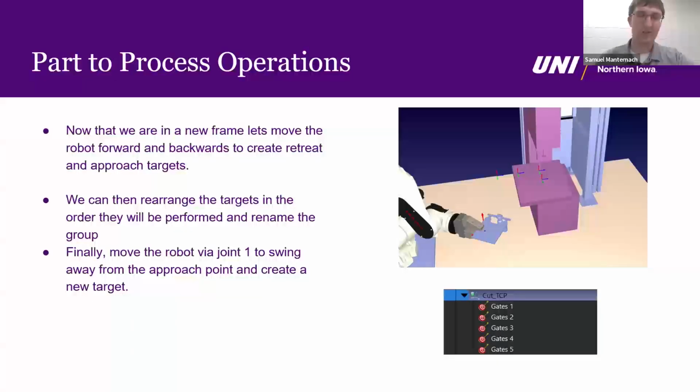The second one you made, which is our start of cut. The third one you made is going to be retreat 2. Fourth one, retreat 1. And your fifth one is going to be the retract point. So in order to make everything easier on ourselves, we're going to line it up so that they're all named in a way we can understand.